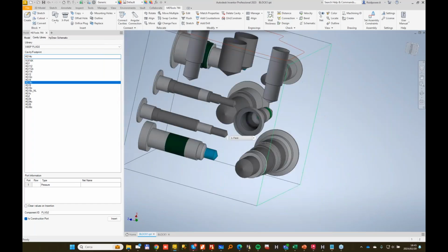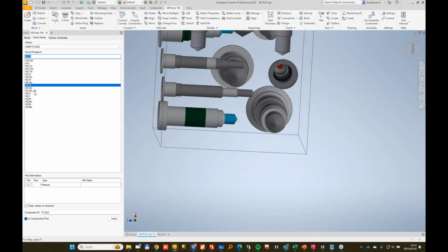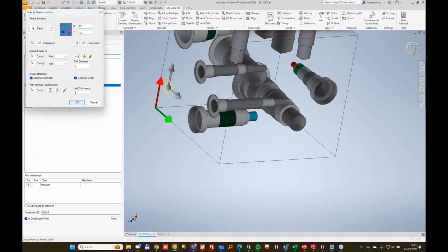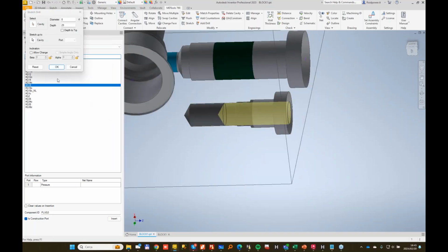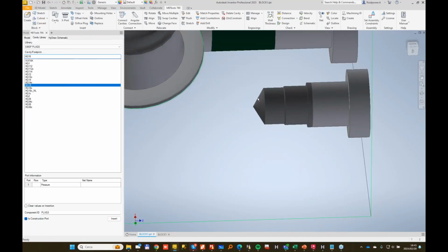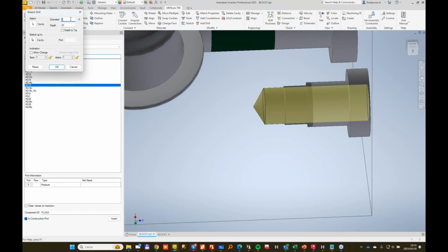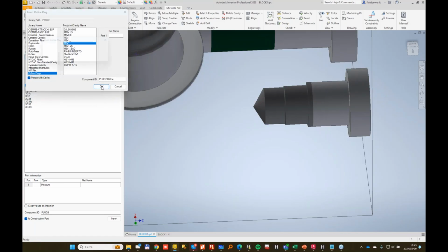A common support request I get, and it's really always simple to answer, but since it's common, let me clarify here also. The orifice is added below the last step of the actual cavity in the block. So if this drill is 8, you will not be able to insert an M8 orifice. You will get an error.